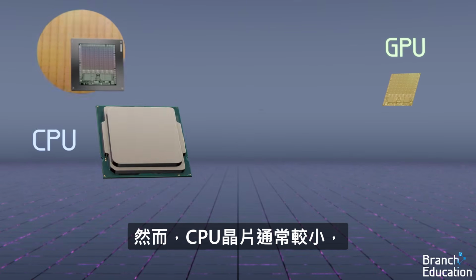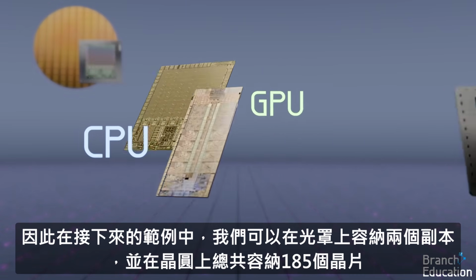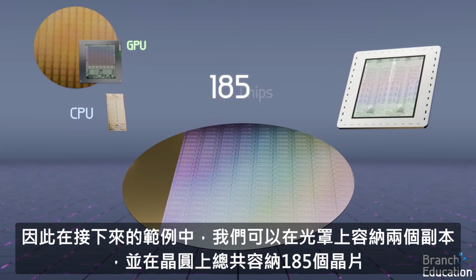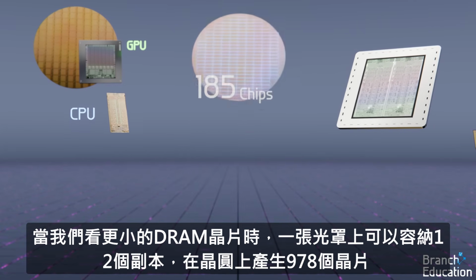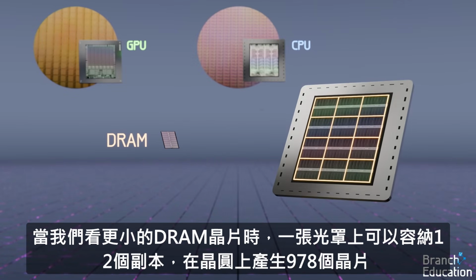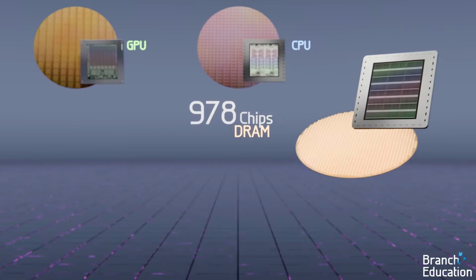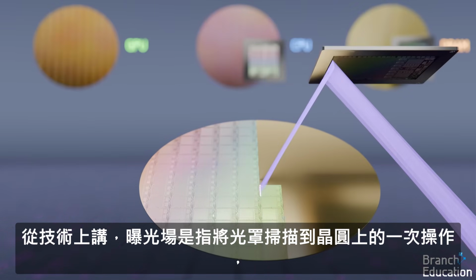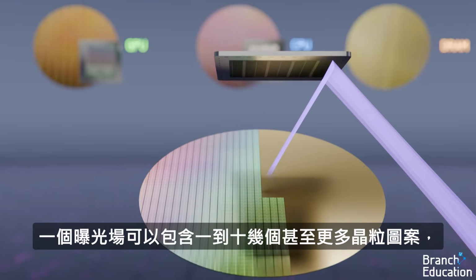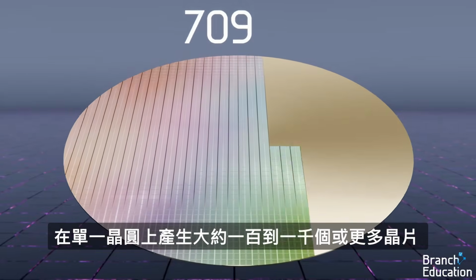However, CPU chips are typically smaller, and therefore, in the following example, we can fit 2 copies on the mask and a total of 185 chips on the wafer. When we look at even smaller DRAM chips, 12 copies can fit on the mask, yielding 978 chips on the wafer. Technically, the exposure field is 1 scan of the mask onto the wafer, and an exposure field can have anywhere from 1 to a dozen or more die patterns on it, yielding around 100 to 1,000 or more chips on a single wafer.